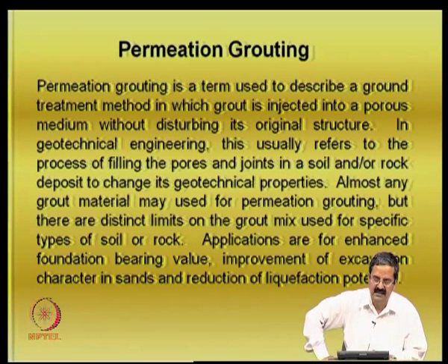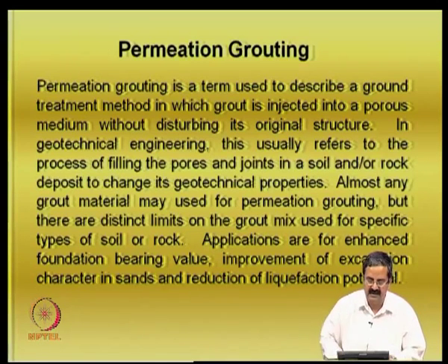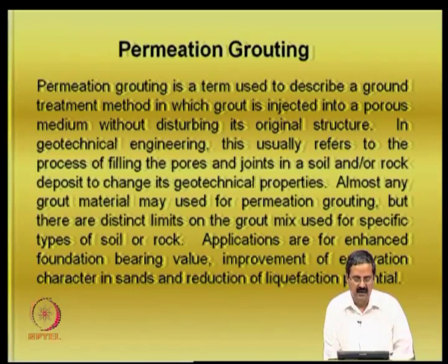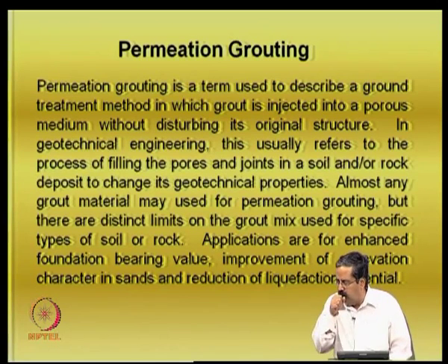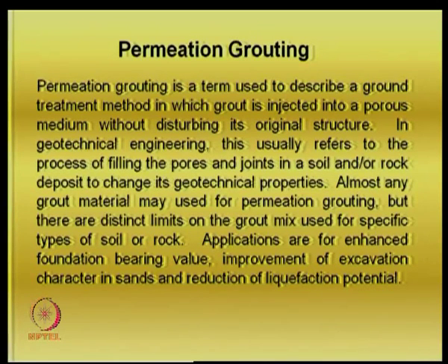As I said, it is just to fill up the pore voids, and it essentially fills up the pores and joints in a proper way. And the advantages, as I just mentioned, are enhanced bearing pressure, improvement of excavation character in sands, and reduction of liquefaction potential.